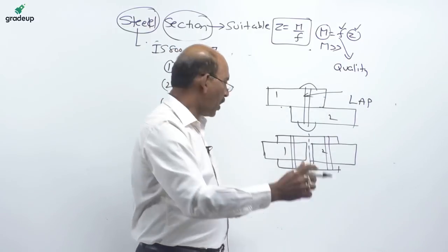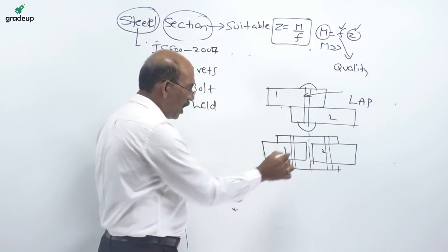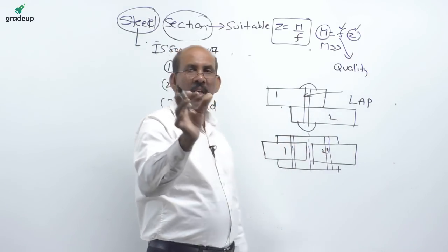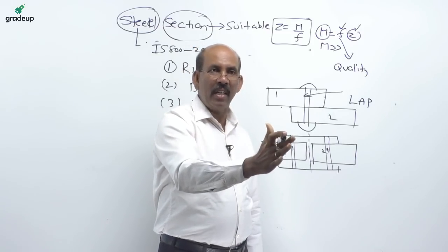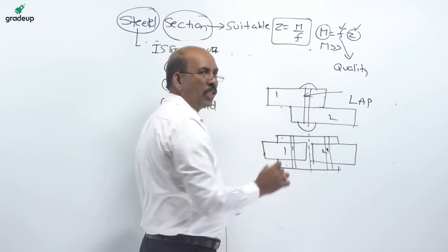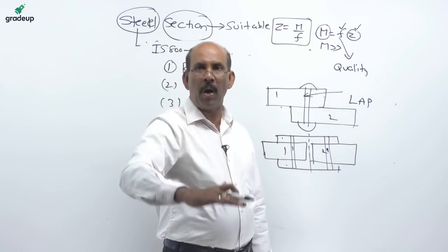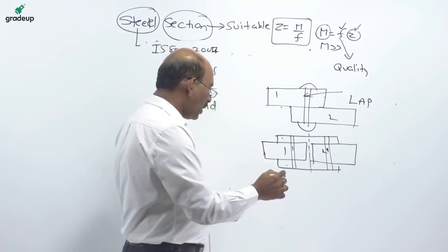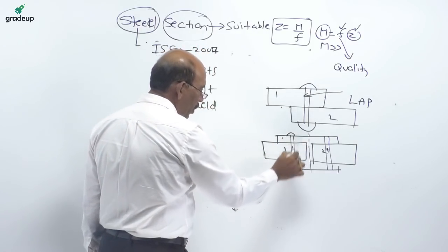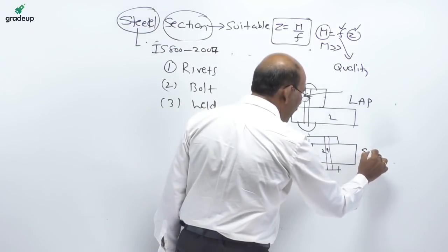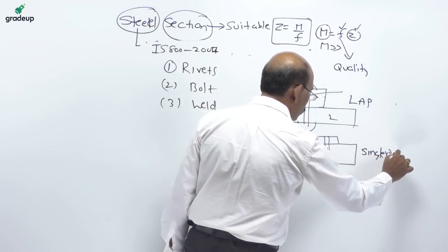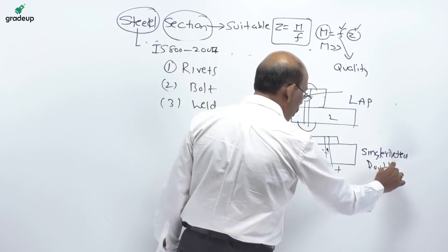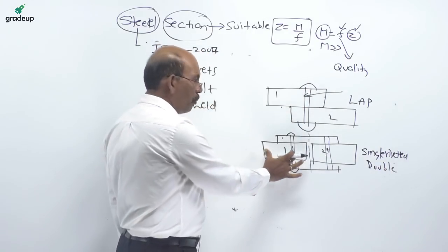So this is the joint. Mr. Sudhir, you can see on either side of the joint, I have only one rivet here, one rivet here. That means we say it is a single riveted, double cover butt joint. The cover is on top and bottom, so two covers are there, whereas the rivet is only one. That is the failure of this particular rivet. You can see here, this is a single riveted, double cover butt joint. So this is the meaning of what a butt joint is.